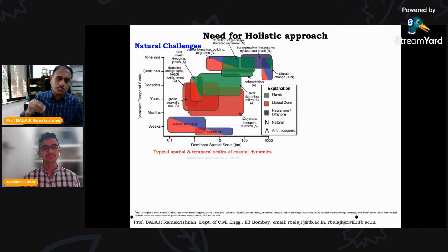When you go to the beach, you see the waves are of the order of half a meter, 1 meter height, and so on. And during the monsoon period, or maybe the cyclone period, of which I really don't advise you to visit the open beach, okay, you get to see in the newspapers waves of the order of 2 meters to 5, 6, 7 meters. Really high and steep waves approach the coastline during these extreme events. But the natural period of these waves is of the order of 5 to 15 seconds.